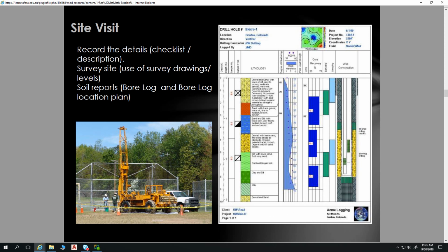With our site, we're going to have to know what sort of soil we're building on. I'd say that looks like an American picture, and that's not your standard. So typically you get your soil sampled. It's a hollow core drill tube on the back of a 4-wheel drive, like a Land Cruiser type setup, with a hydraulic drive. So much significantly smaller units than this.